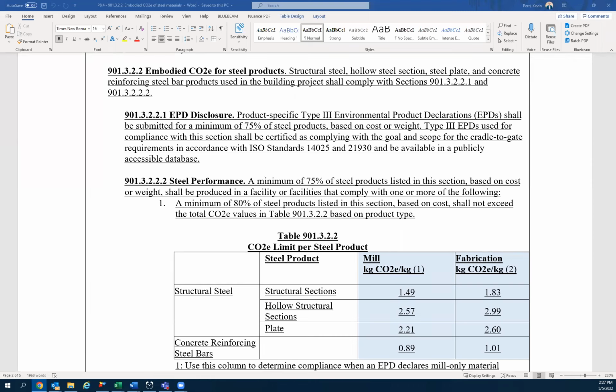Compliance for this could potentially mean indicating EPDs and global warming potential in the project specifications, and at the time of permit intake indicate how much of the purchased materials will be reported. Prior to occupancy, project teams can illustrate compliance through a material global warming potential spreadsheet and supporting EPD documentation. So I propose the adoption of 8.4.